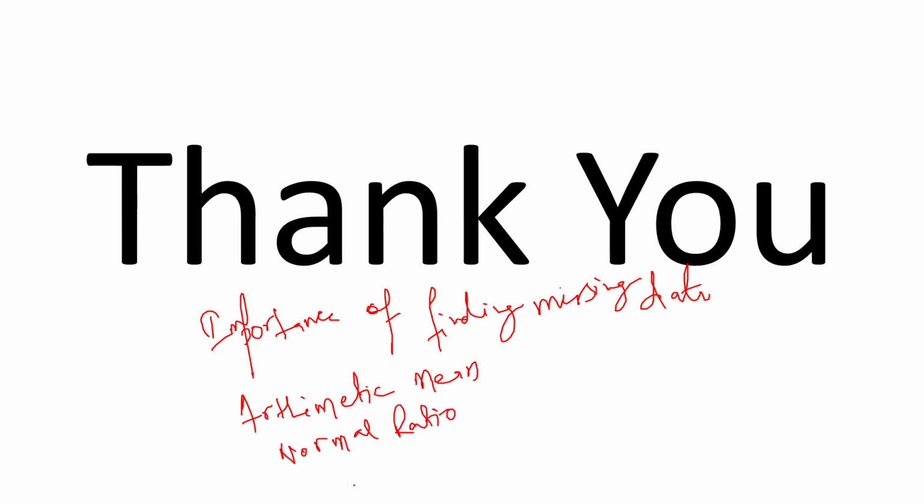And that's the end of our lecture on estimating missing rainfall data. To quickly recap, we saw why finding missing rainfall data is important, and we discussed three important methods: the arithmetic mean method, next the normal ratio method, and the third one which we discussed is the distance power method, in which the weight of each rain gauge station is considered, and the weight is inversely proportional to the distance or some power of the distance.